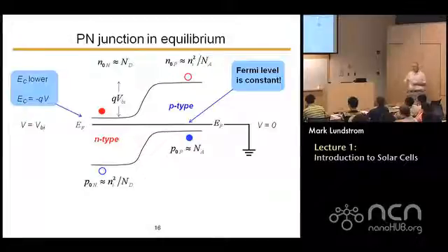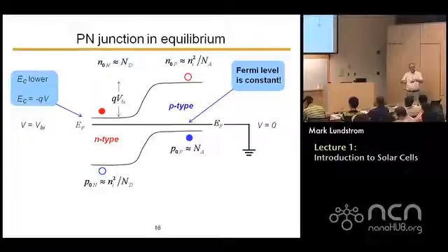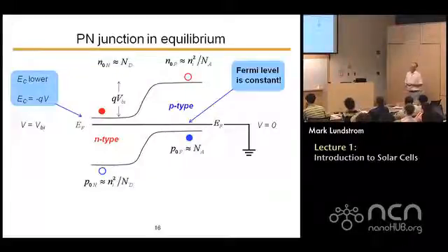And this is a really interesting voltage, that we talk about a bit when we do semiconductor courses. You have a p-n junction, you go in the lab, you put your voltmeter across the p side and the n side. What do you measure? Nothing. But the voltage is there. All right? And this takes a little bit of discussion that maybe we can do at the break or something.